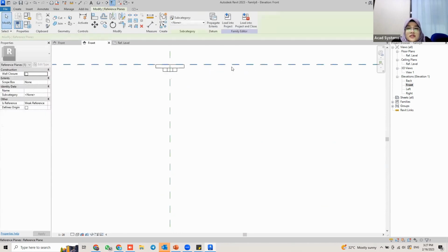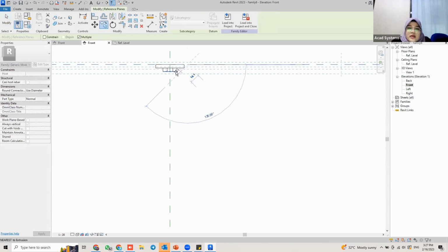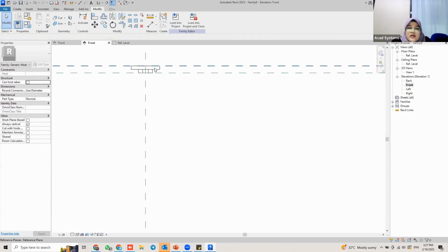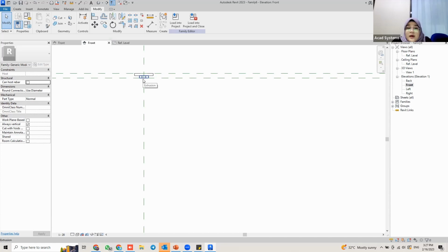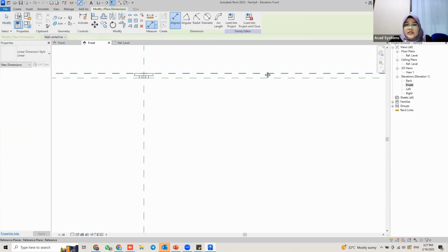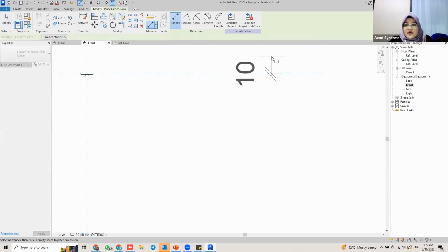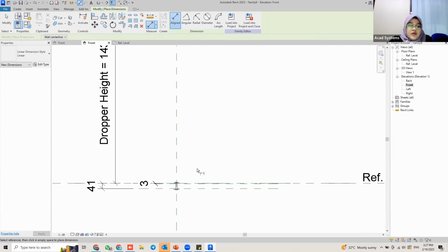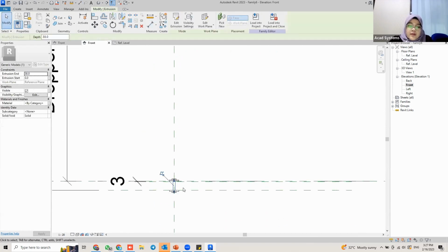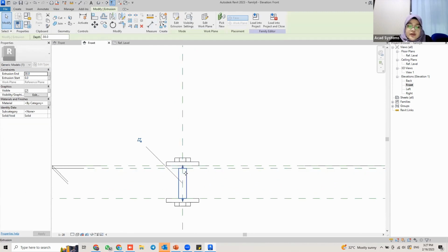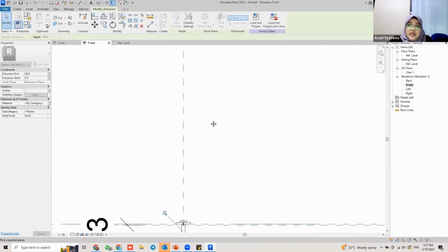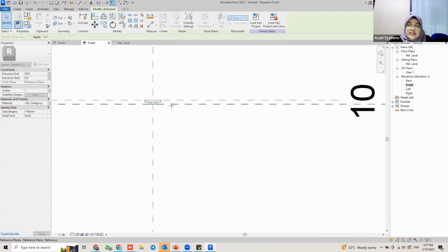Okay. Just copy this one, bring it down, and make it the thickness of the bolt and the plate. Okay, then going to dimension it. So this one will be 10. So right now I will copy the rod that I just copied just now, and going to set the edit work plane, pick a plane, okay, and I'm going to pick a plane that I created just now.